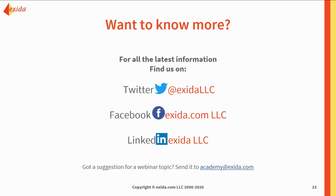If you want to achieve a SIL 3, there are probably a lot of different cases, and you need to know your application. You need to know exactly what's going into this, and we can talk more about that if we know specifically what's going on. But on this general broad scope, we're not going to dive into that yet. We're going to get more into that when we cover partial stroke testing and the pre-assembled valves as well. So we're not quite there yet. You're a little ahead of our webinar curve.